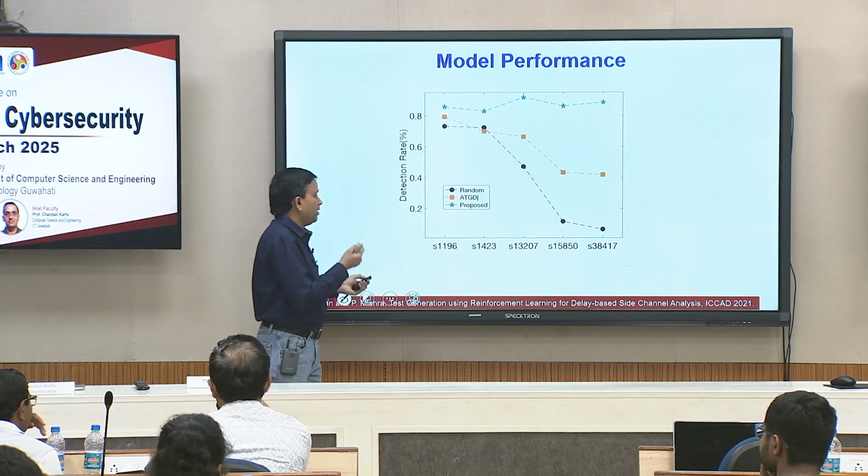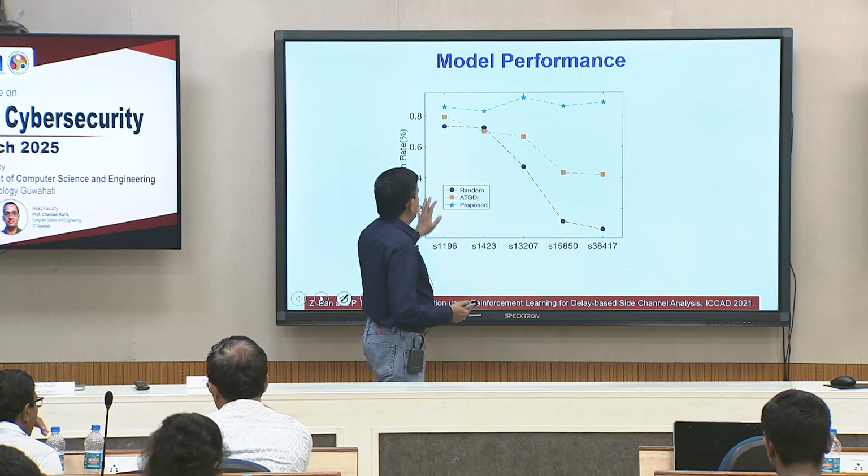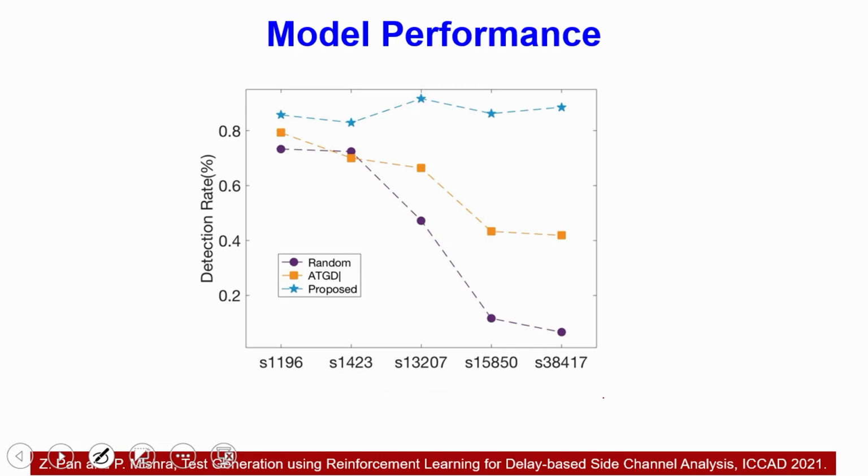And again, with any test cases you run, whether delay or not delay, you basically want to show for different designs what your Trojan detection rate is. So, in this particular case reinforcement learning is able to get close to 80%, whereas for many others, when the design size increases, I know all of those are silly designs anyway, even within themselves they are in increasing order, this is about 10,000 gates. So, even with the existing approaches, accuracy goes down pretty drastically for delay based analysis.